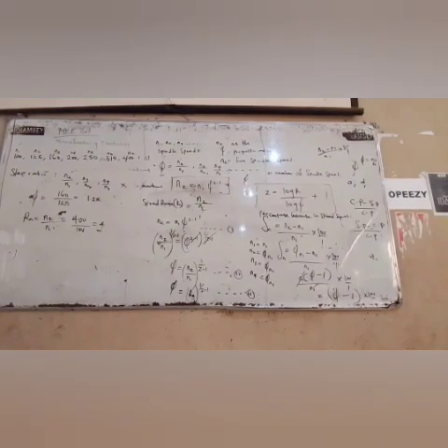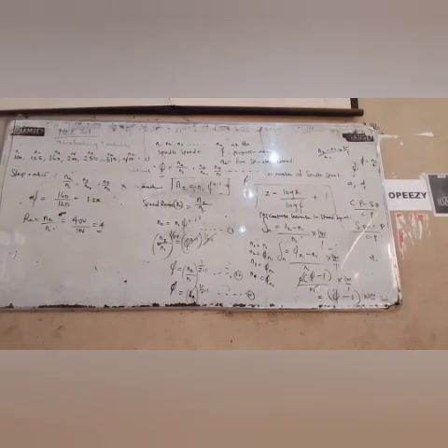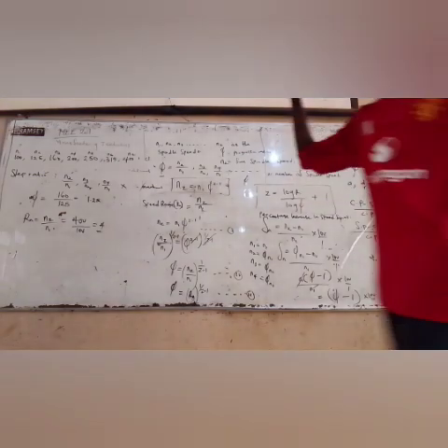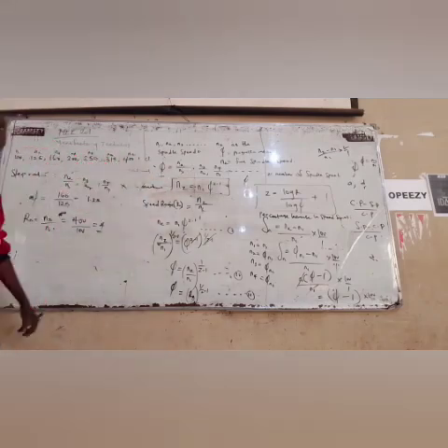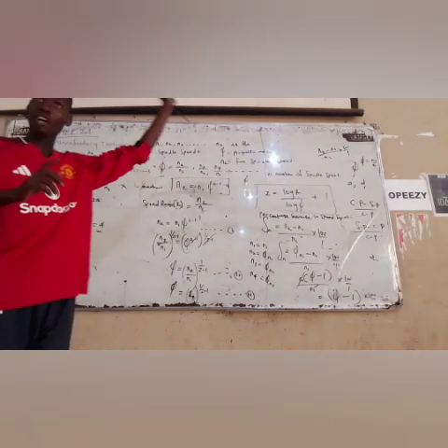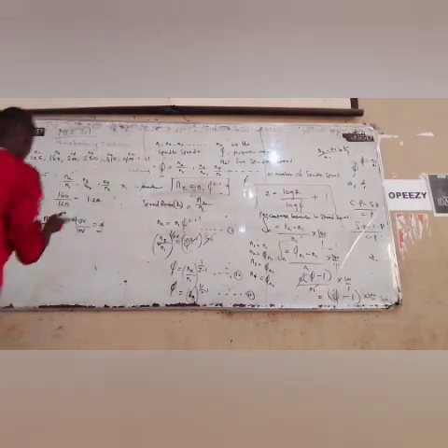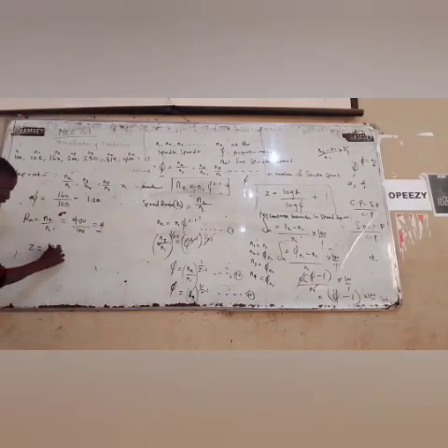Now the next one is the number of steps. You can calculate it in two ways. The first way: what is the number of speeds here? 1, 2, 3, 4, 5, 6, 7. It is 7. Or you use this calculation: Z is equal to log R over log.